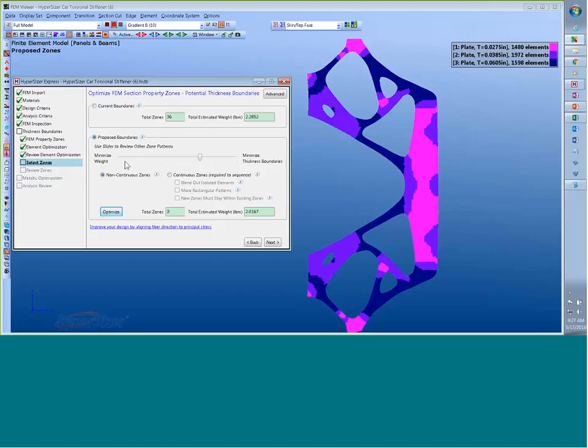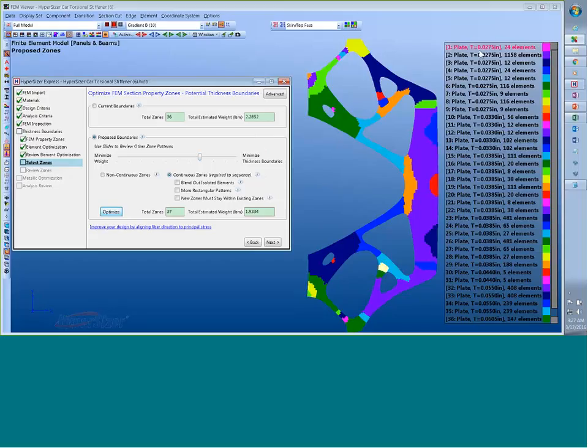You'll see this a lot today, so I need to describe what's happening. Basically, we have 3 unique gauge thicknesses, but again, they're spread throughout the part. The continuous optimization here now identifies each of these as being separate. So you can see several places where, as I go through here, this is 3.85, 3.85, 3.85, 0.33 is 0.33. There are 0.33 thicknesses here and here, but a different thickness in between.